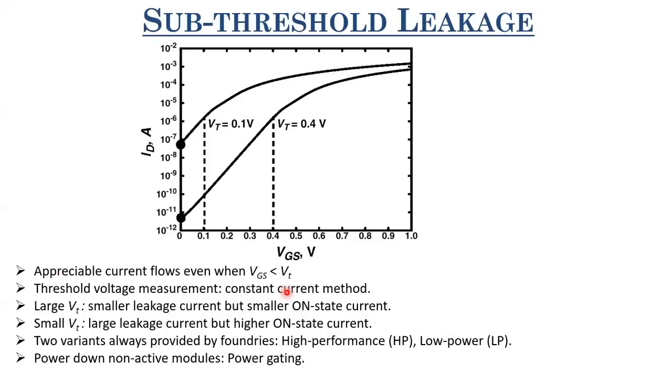Also, during runtime, there are several tricks that these industries use in microprocessors. One of them is known as power gating. So what exactly is power gating? At any point of time on a chip, all the gates are not being switched on or switched off. Some of them are in the static mode. Even if you're making your gates with high performance transistors, some of them would be in static mode. Only some of them would be switching, not all at every time.